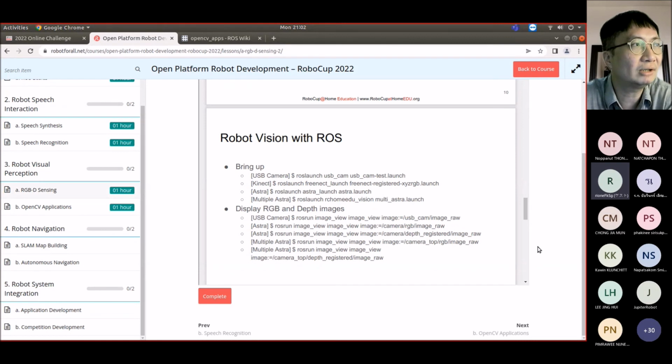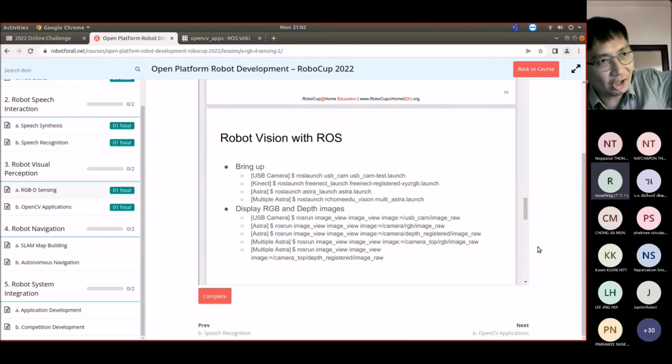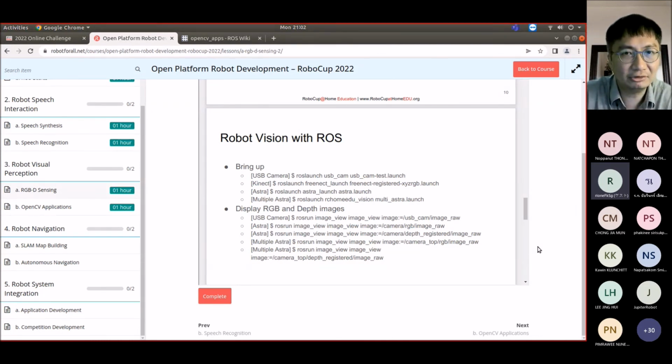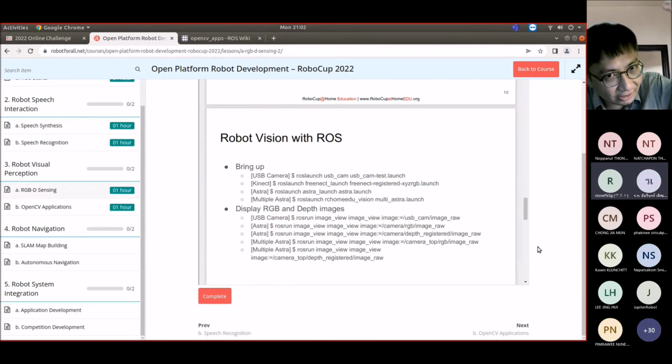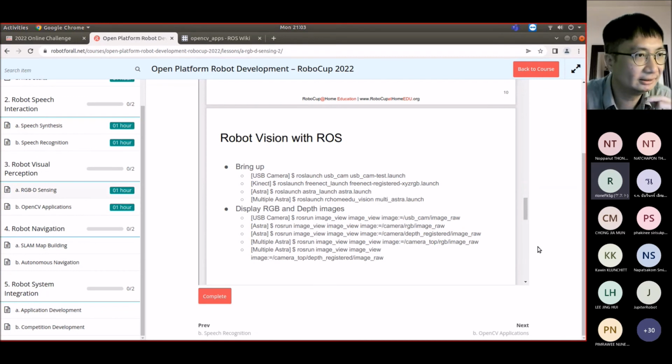And if all this is okay, then the only thing I can see is I need to check the log when you run your Astra. If you remember, when I ran my Astra we got a lot of log coming out. So I want to see if there's any error over there. Anything red you need to notice. I'm also afraid that either your Astra package is not correctly installed or your sensor might have some problem. This one I don't know how to tell you unless I see your log. But these are the things that you can check.